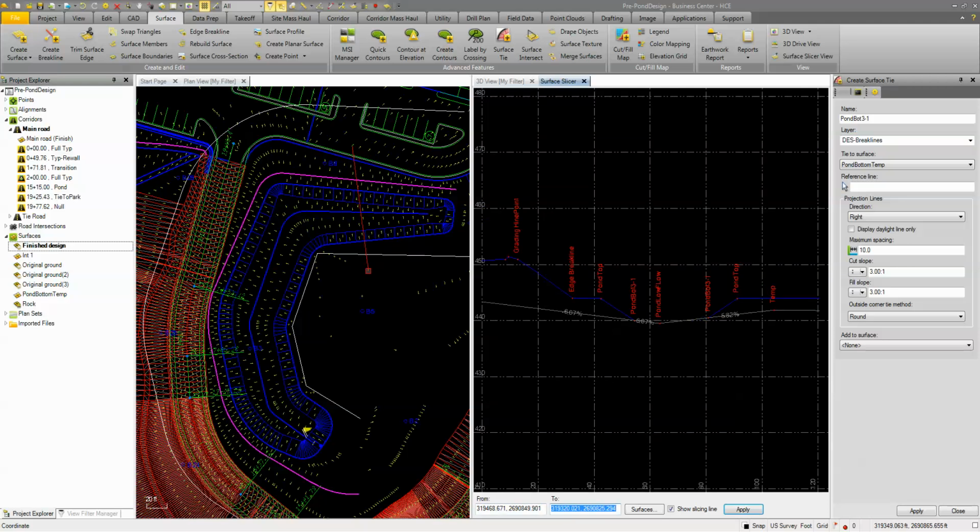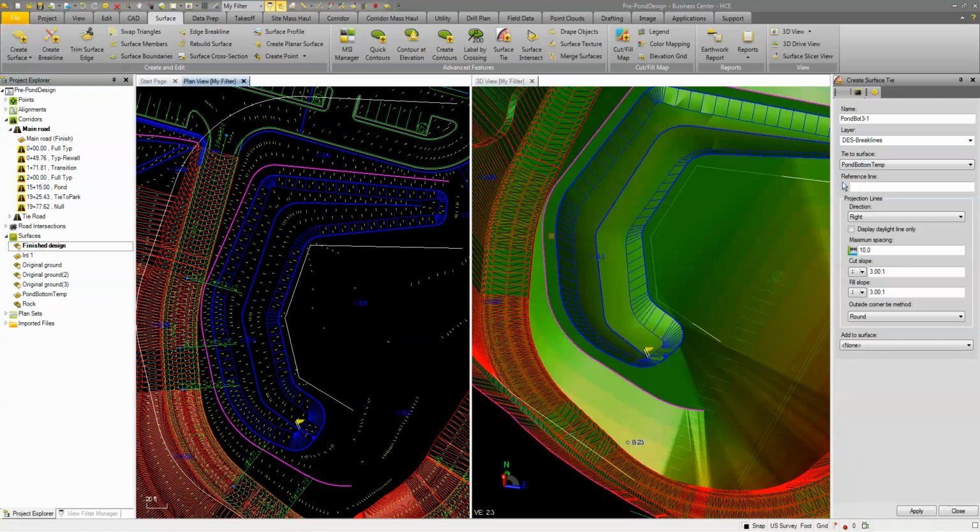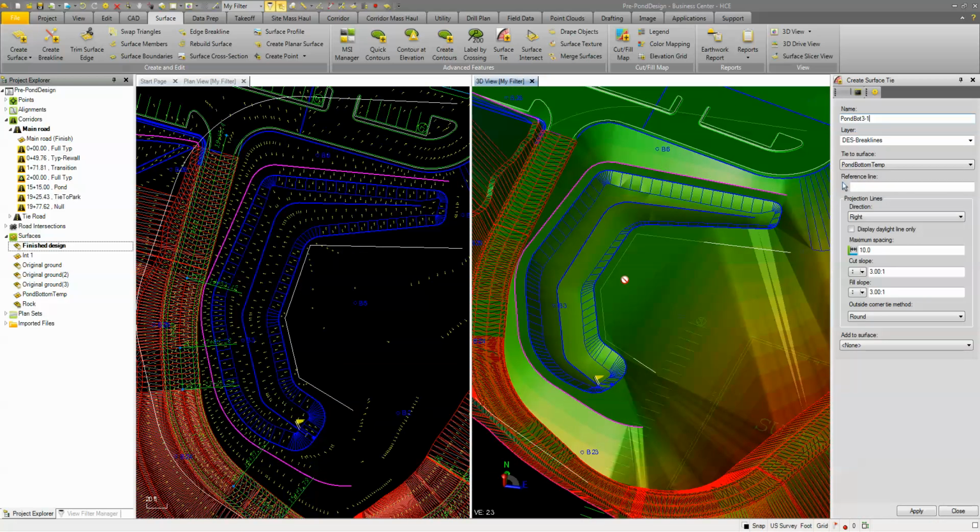You know, so we're looking pretty good, right? So we can do some adjustments here. We can move this guy around. It'll readjust our surface and whatnot. But it kind of gives us an idea. What we need to determine though is this pond adequate for our storage? So we're going to do some trial and error here, make some adjustments, and determine whether we need to increase or decrease that pond. All right, and we'll clean this up as well. So we'll show you that next.